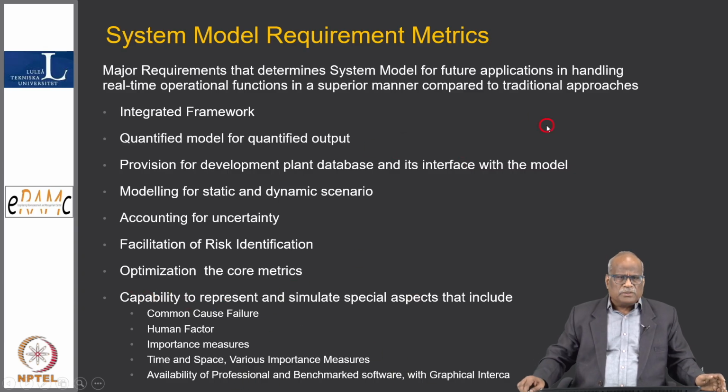It's called common cause failure, yes, because we will be showing in the subsequent presentation how important it is. If we do not take into account common cause failure, then the result could be over optimistic, and it might not give a correct estimate. Take two redundant components.